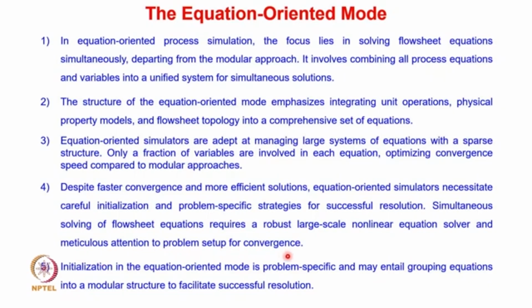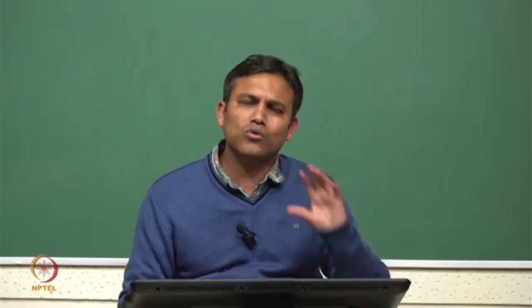So what initial values you are giving, what nonlinear equation solver you are using, the solution depends on these to a large extent. So initialization in the equation oriented mode is problem specific and may entail grouping equations into a modular structure to facilitate successful resolution. In some cases, whenever you have a large number of equations, you sometimes group these equations in a manner similar to a modular approach.